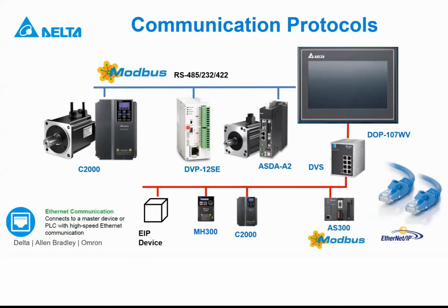All these PLCs have modules, a card you attach to them that reads your sensor, depending on what the output of your sensor is. Maybe your sensor output is current, or maybe it's a temperature sensor like PT100. So you have a module you connect to read your sensor. The PLC you use depends on the price factor and on the functionality.